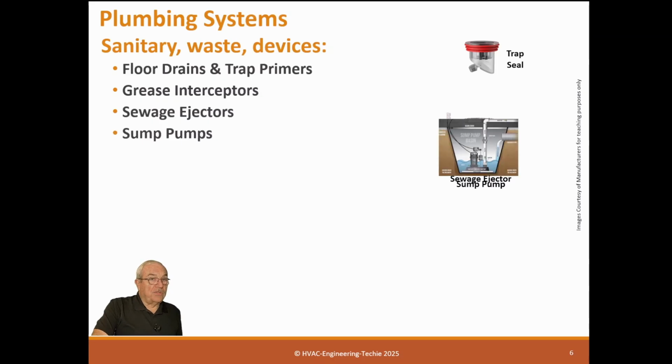Sump pumps are similar, but they're not for sewage; they're just for clean water, like buildup from rain or condensate or something. Code requires sump pumps in every elevator shaft, so the elevator shafts have sump pumps in case water enters, so it doesn't get into the elevator.